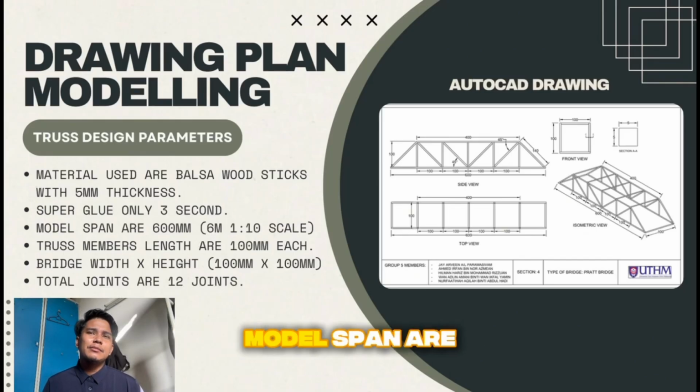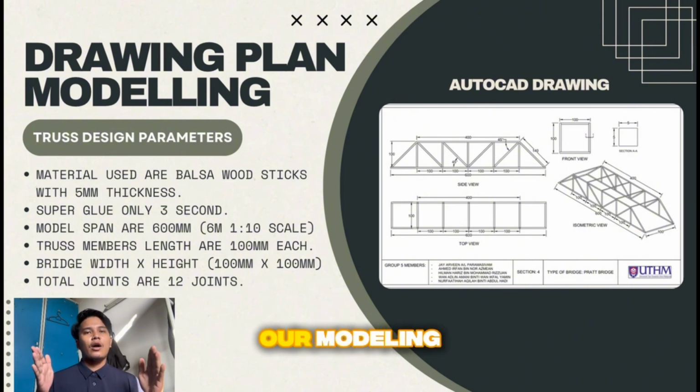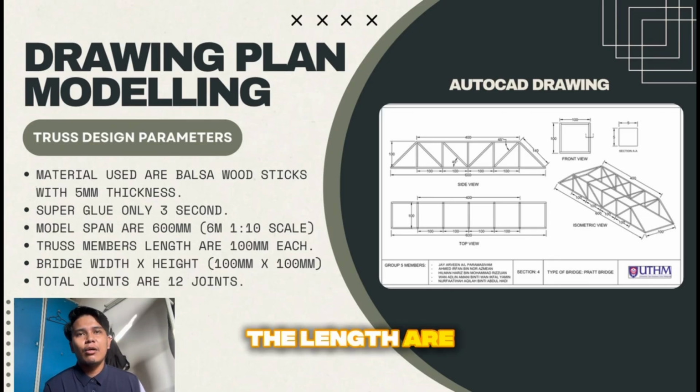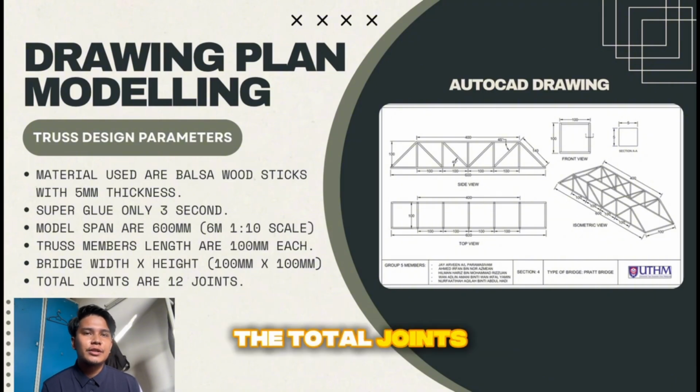Next, the maximum model span is 600mm, which is the total length for our modeling, which is a 6 meter, 1 to 10 scale. So for each member, the length is 100mm each, and the bridge width and height are 100mm times 100mm. The total joints for this modeling are 12 joints. So I'm going to pass to my next member.